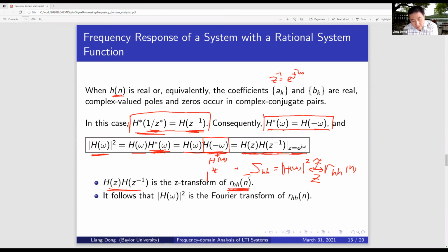We have already used that when we are dealing with any signal X, right? Here, we only changed X to little h. So we think this system is represented by a discrete signal h[n]. Then we can talk about similarly the autocorrelation of the system. But the system itself, there's no autocorrelation, simply meaning that h[n] convolved with h[-n]. We got this autocorrelation of h. And then its Fourier transform, or the Z transform, becomes this quantity.